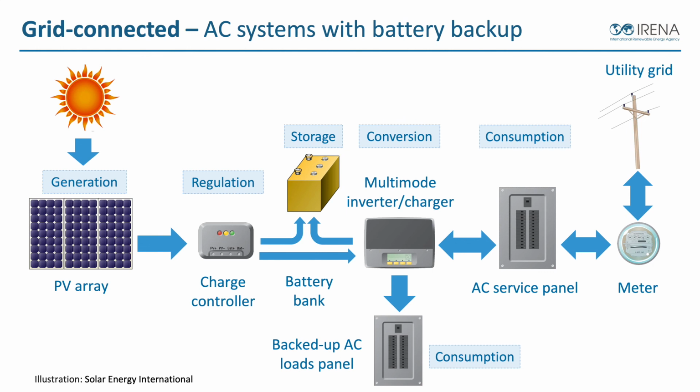It can synchronize with the utility grid and sell electricity into the electrical grid, just like the previous inverter we just discussed. It also, being an inverter charger, can take an AC circuit from the utility or an AC supply and charge the battery bank as well. So that battery could be charged from the AC source, which is in this case the utility.